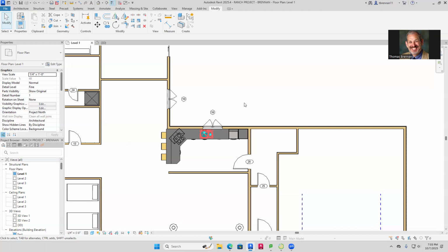Let's see what our levels are. Your levels are 10 feet. Now you can change that. Click on the line right there and change it from 10 feet. You can make it 12 feet, if you want to make it taller. Then you would actually have taller ceilings. Then you could click on your ceiling right from this view and tell it you want it to be 12 feet. Not 102. Oh boy, it's quite literal. Okay, that gives you a little bit more.